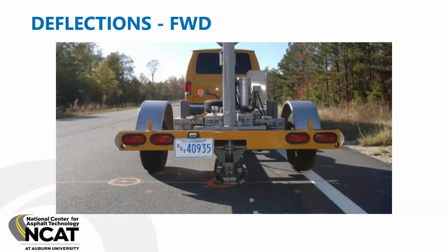One of our biggest tools we use here at the track is the deflection basins we get from the falling weight deflectometer, or the FWD. On the track, we test this 3 Mondays out of the month because, under the accelerated traffic damage that we do here at the track, it's necessary to get that full picture. Out on an open road, you may not do it that much, but we're fortunate that we can shut the track down and don't have to put up a lane closure to run these. The data they provide, without being destructive, is invaluable.